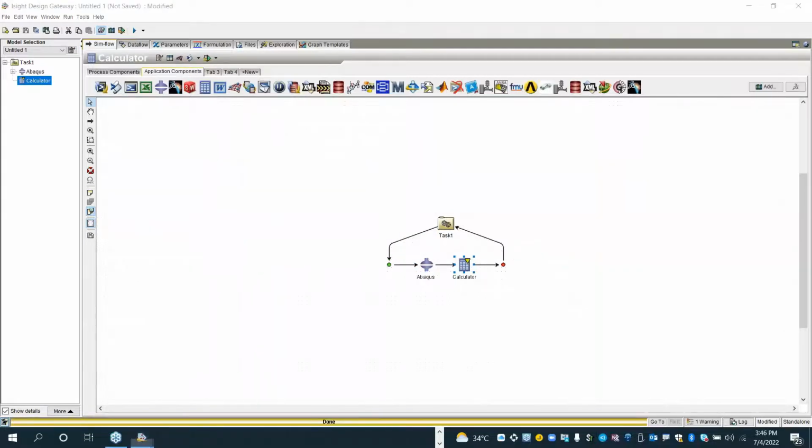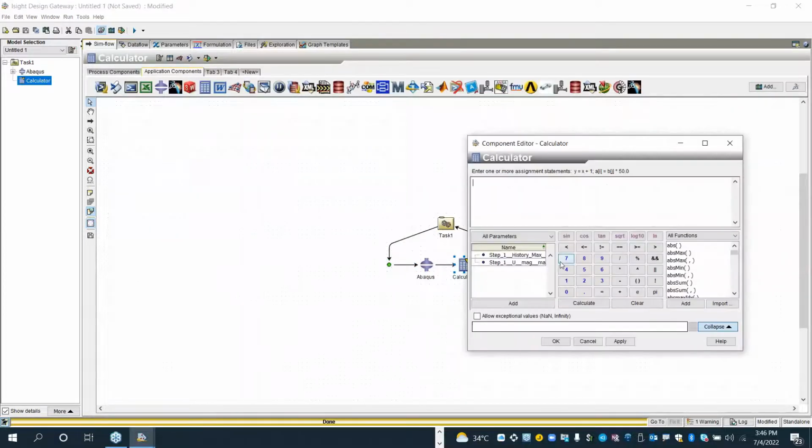So here I see both the parameters that I've picked previously as outputs. So they become the input to this activity, as you see. So both my mass and the displacement information is here. Here I'll add a simple calculation. I'll call it cost. So cost is nothing but equal to the mass times, I'll give a factor to it, 0.5.